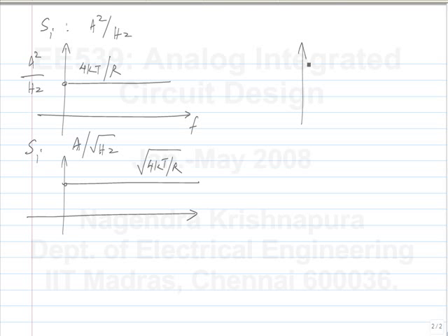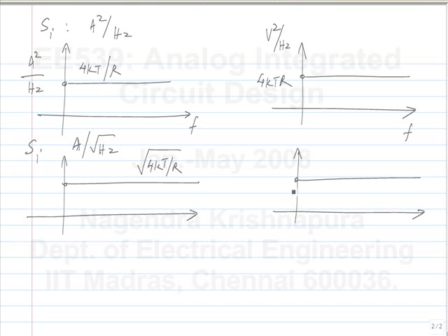So similarly for the voltage, the units of spectral density of voltage is volt square per hertz. And again it's quite common to see the square root of this plotted, volts per square root of hertz. Now, of course, you can go and calculate this for every case, but it's good to remember that kT is 4 times 10 to the minus 21 at room temperature. So it's a useful thing to remember.